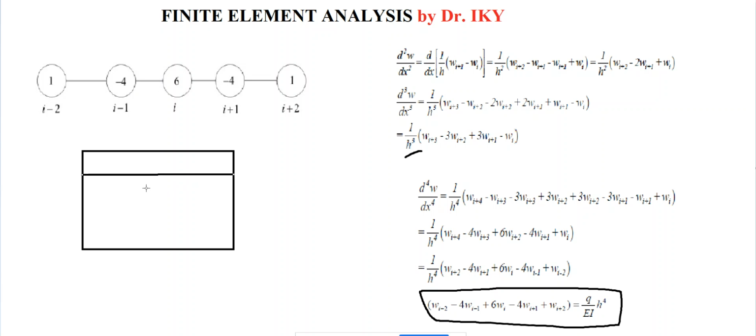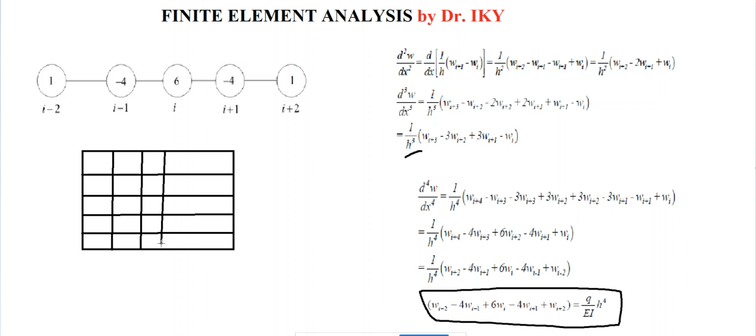We will just try to create a mesh with equal numbers first, maybe, and then to reach more detail, you can increase the number of meshes, or for decreasing the time, you can make a coarser mesh.